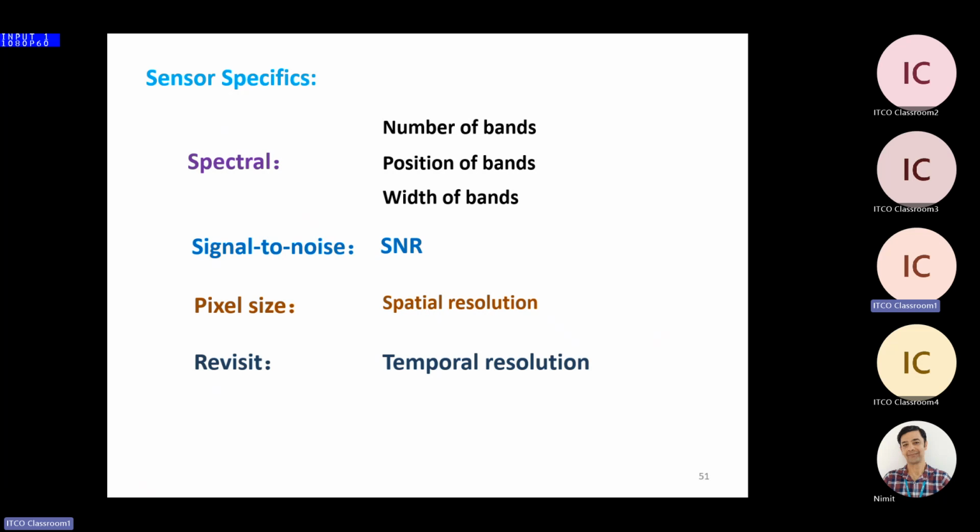Landsat is 30 meters by 30 meters. MODIS is 1 kilometer by 1 kilometer. So they have different pixel sizes. Then GOCI is geostationary; each day it can measure 8 times, 10 times, but MODIS or OCTS normally, for the low latitudes, measure once per day. So they have different temporal resolutions. So it's important to have a good understanding of what these sensor specs will impact in our retrievals.